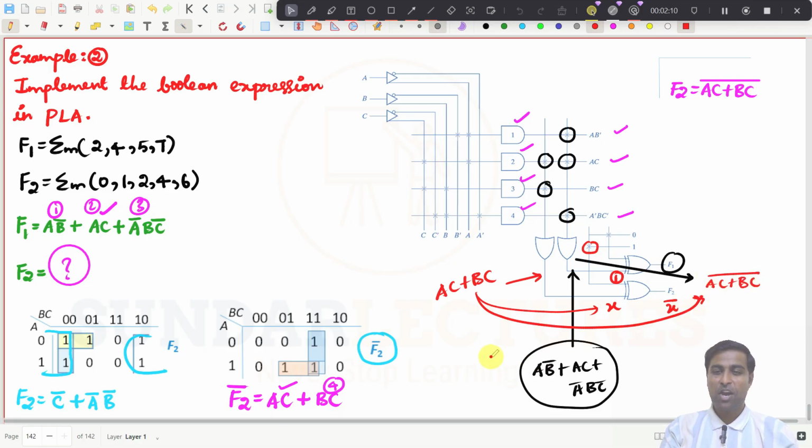Try to understand. The idea is that getting the package is the difficult thing here. I am getting a package with 4 AND gates and 2 OR gates as a PLA. If I had not done this, I would have to get a package with 5 AND gates and 2 OR gates. So you can implement as many problems as you like. It is very simple now.